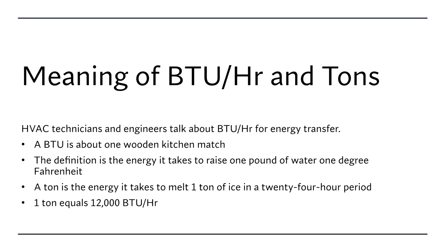But that is how we actually classify that, and that's generally what that's about. So if I take my, let's get a calculator out here real quick, 20,495 divided by 12,000, I get a 1.7 ton refrigeration load, or heat pump, or air conditioning load.